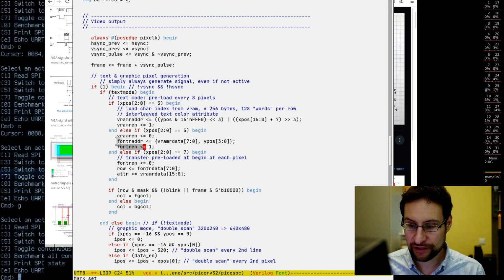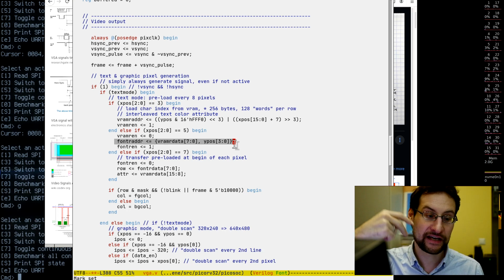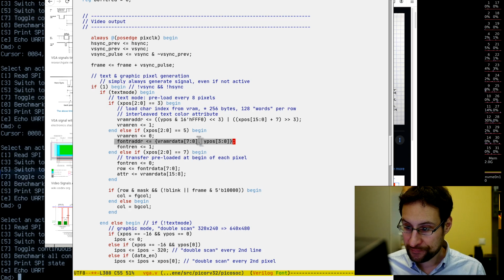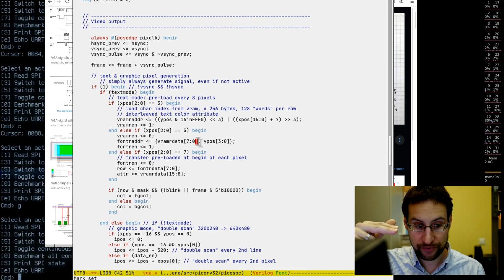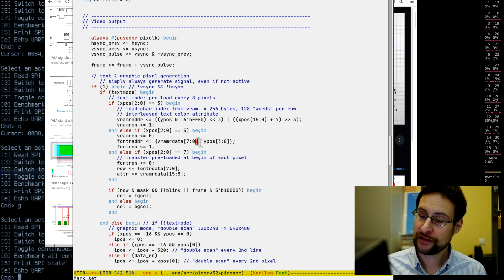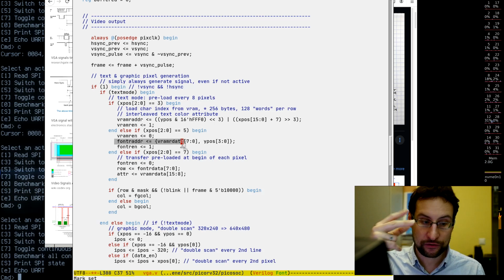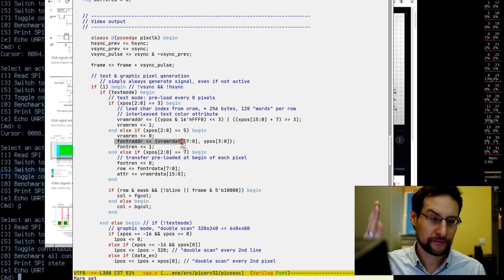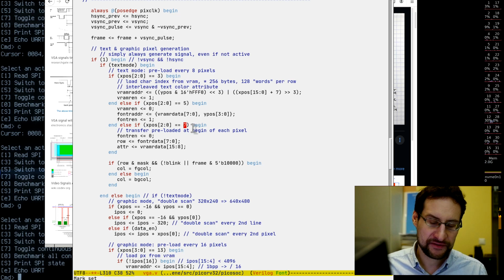We enable the read enable and load it with the address of the VRAM data, again like R or something. This is multiplied by 16, for 16 bytes per character, 16 pixels high with 8 bits each, just similar to a VGA text mode memory. We output this address, and again this needs 2 clock cycles to have valid data on the memory output. This is then the 7th, aka the 8th pixel here.